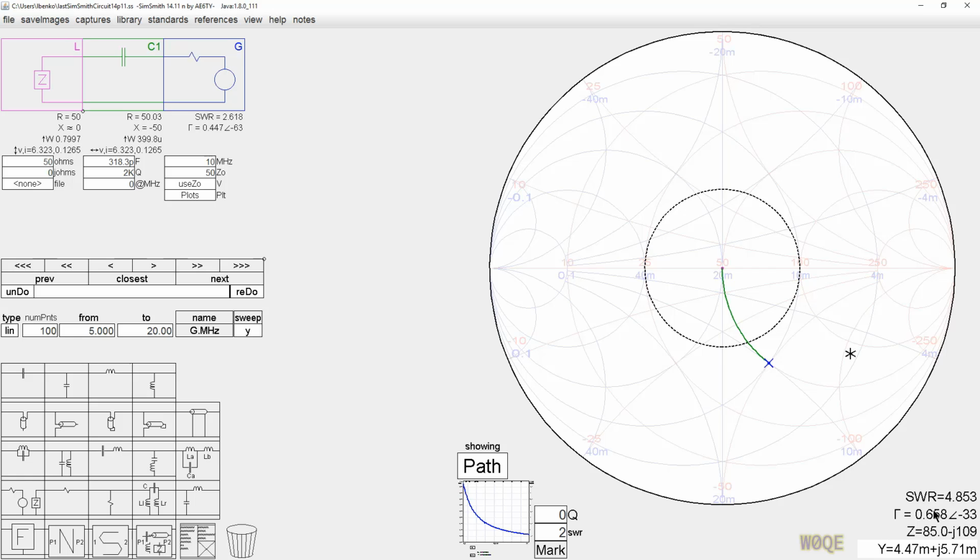This displayed on here, which can be thought of as, like I said, a digital display of the analog Smith chart, has 4 pages of data. This is page 1. Page 2 is an admittance-only page. The admittance-only page is not very exciting except for this one line right here. This tells us that this point right here is equivalent to 224 ohms in parallel with 90.8086 picofarads of capacitance at 10 megahertz. Click again.